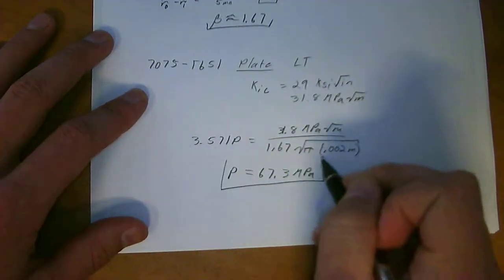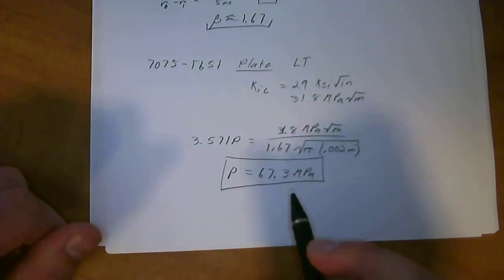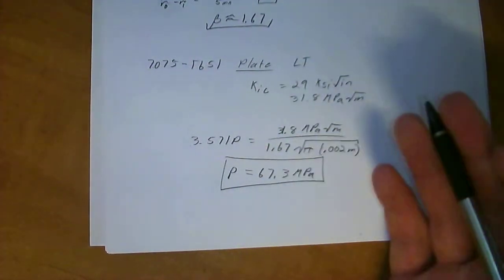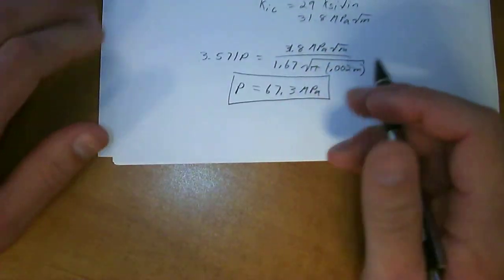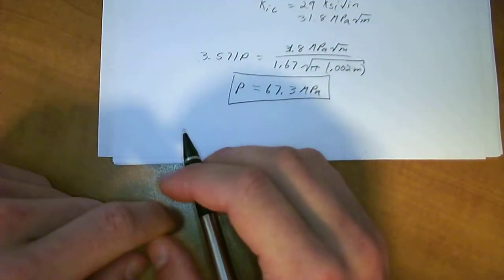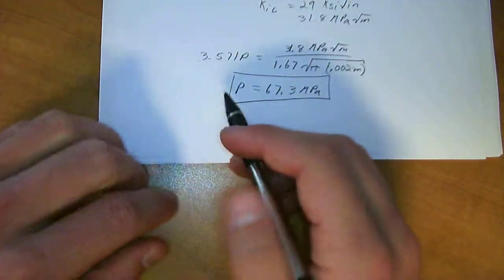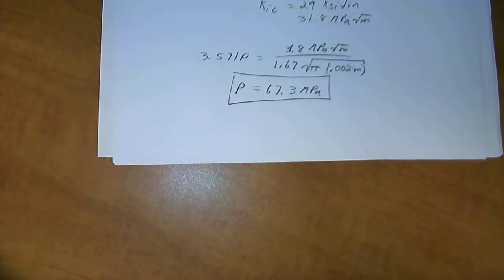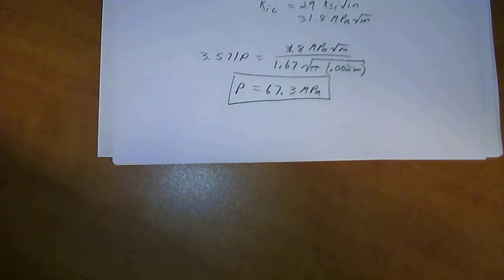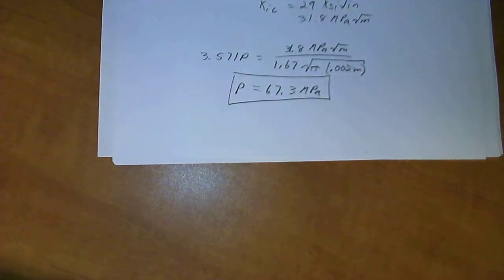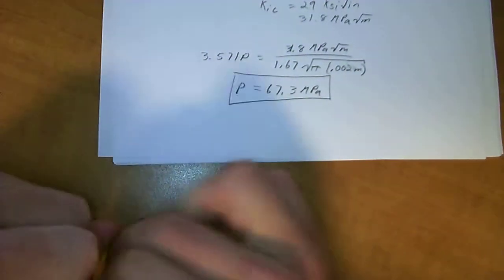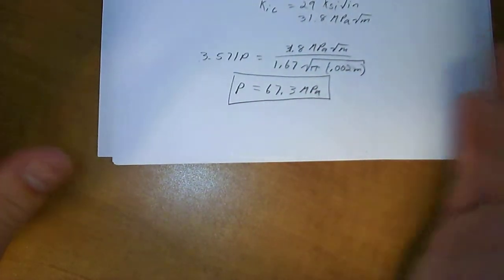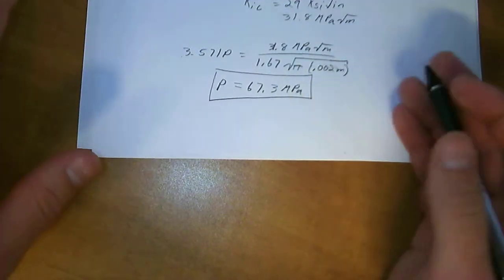So now, moving on, we need to check sigma to find out if it's going to fail because of fracture or because of yield first. Fail due to crack growth prior to permanently deforming. So basically, is it going to crack and break before it stretches? If it stretches, then good. The tank is self-adjusting to increasing pressure, but if it breaks, then you have a tank failure. So we want it to fail due to yield first. I'm actually just going to start this on a fresh page.